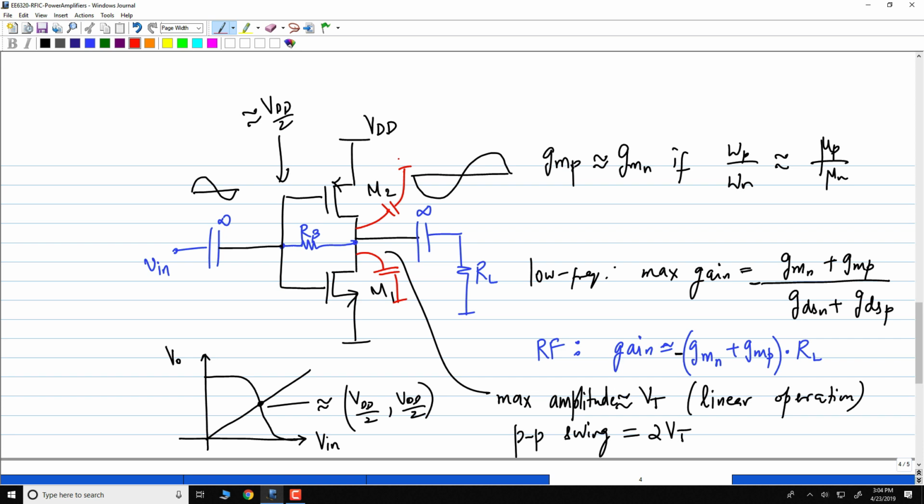The transistor acts as a transconductor, right? So the signal current flowing out splits between the load resistance and the capacitance. The capacitance is typically the drain-bulk capacitance of your own transistor. So clearly there is an RC bandwidth for this circuit. If you go beyond a few gigahertz, it's harder and harder to make this circuit work. Does it make sense?